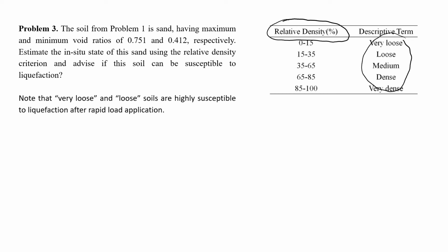Of course, for most engineering applications, we would like the soil to be in the dense or very dense range. In nature, it can be from very loose to medium. So what we will need to do is densify the soil. We can either do compaction, or if necessary for soft material, we can do consolidation.